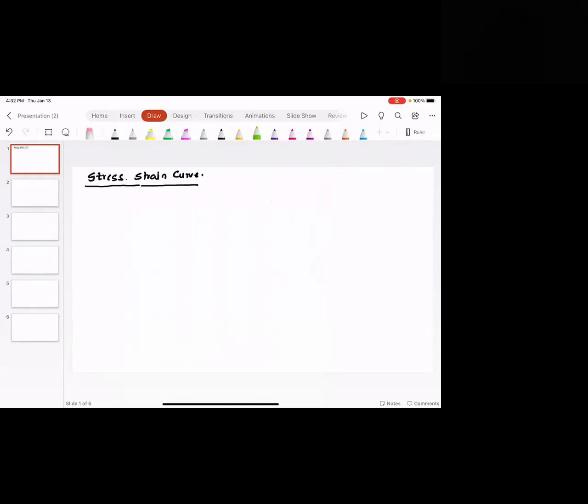Now, in last class, I briefly talked about the stress strain curve for the mild steel. So you have stress on y-axis, you have strain on x-axis, and if you were to apply this stress strain curve concept in practical design, it is only applicable when the loading is quasi-static, which means the component is slowly stressed.